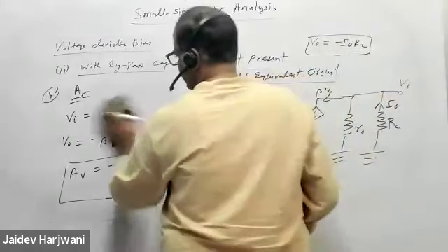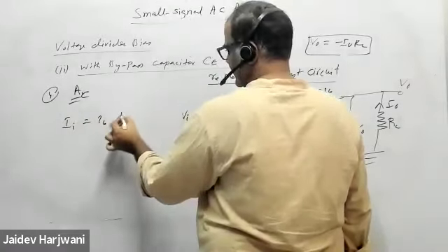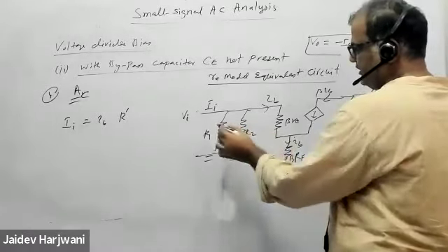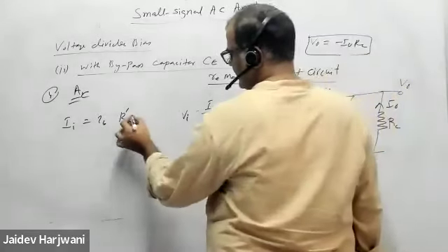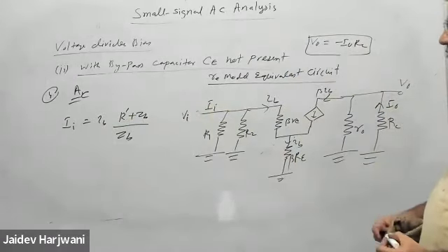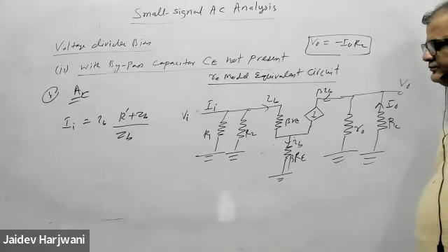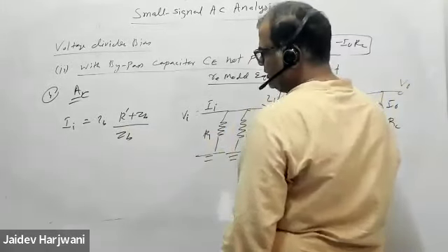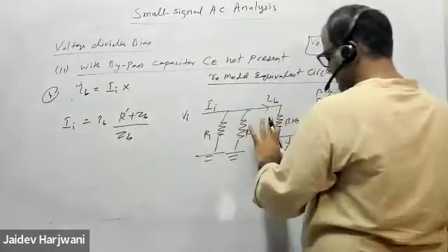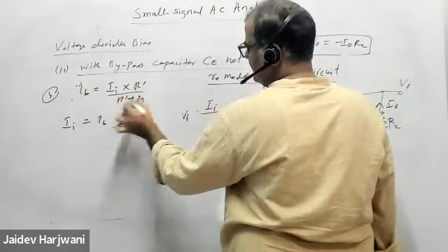So now the input current will be IB into R dash. These are parallel, na. So I will be R dash plus ZB upon ZB. Is that the correct formula? Tell me. Sir, R dash will come, na. Yes, R dash is below. Why will R dash come below? If I have to write IB, how will I write IB? Total current I input into the opposite resistance, over the equivalent R dash. Yes, sorry, R dash and then R dash plus ZB. So R dash will come, correct.